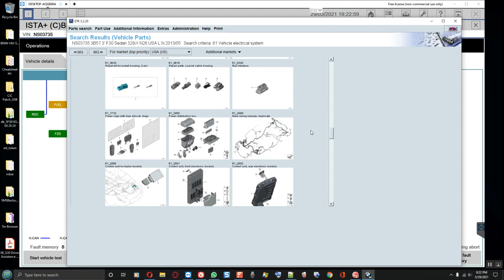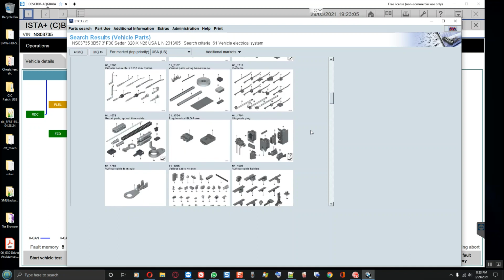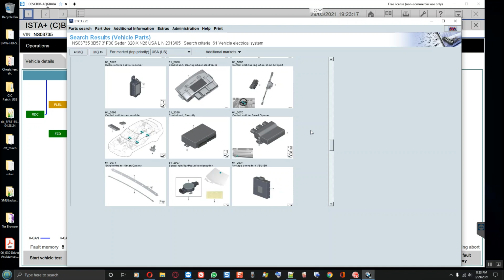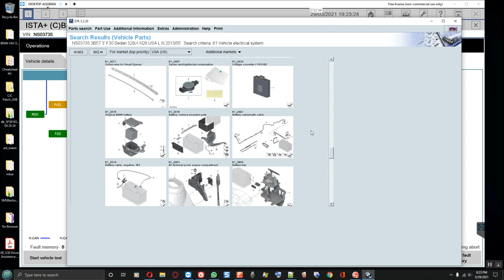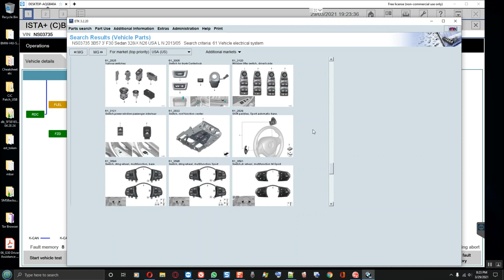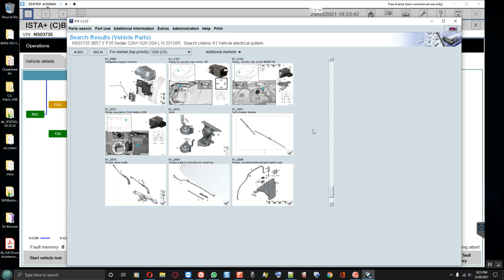I believe it's looking for that pin 19 and 20, that additional signal. You think? For some reason, with the coding, the fault wasn't there before the coding got screwed up, and then we fixed it. So I think somehow the coding variant, now the ACSM is looking for that additional signal that's not supposed to be there with this car. That is why I asked. That's what I'm saying, if we can pull up what it was when I initially hooked up to the car and code that version back into the ACSM.